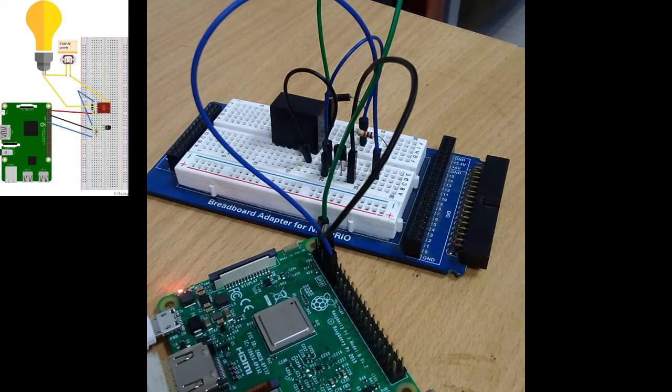When you click on and off buttons in your web page, you should get a tick sound from the relay. If you get a tick sound from the relay, this connection is working perfectly. We are getting a tick sound, so we can proceed to interfacing our home appliances with the NC, NO, common pins of the relay.